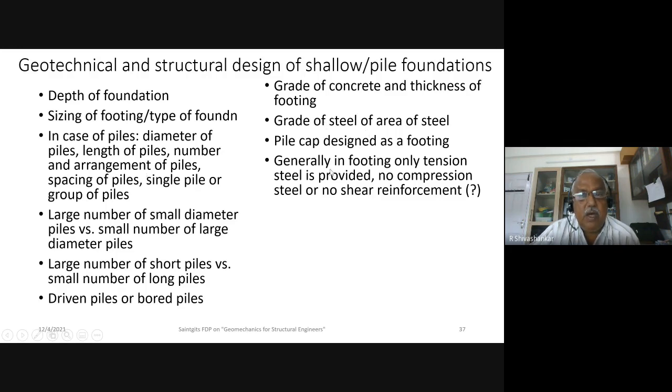Coming to structural design, I know how the soil bears the load, but the load is also transferred to the structure, to the body of the pile. So when I'm applying a load on the pile, it should not get crushed and fail by compression. So my pile should be structurally sound. That means it should be made of strong concrete with sufficient steel.